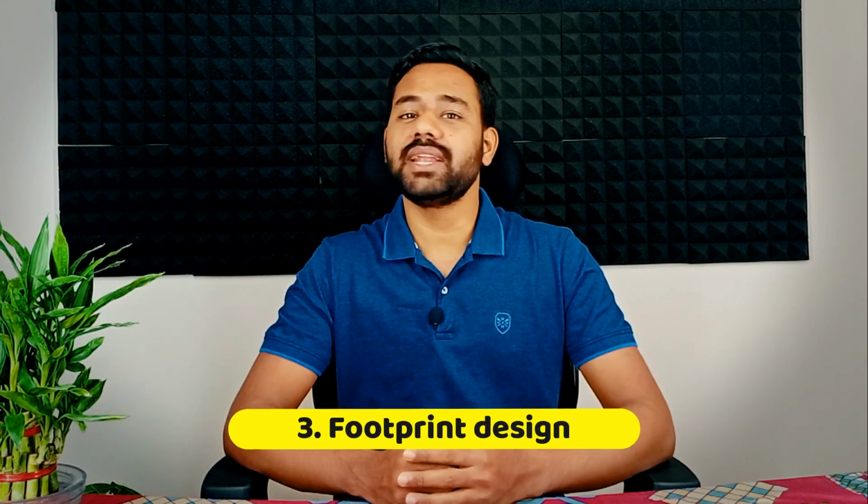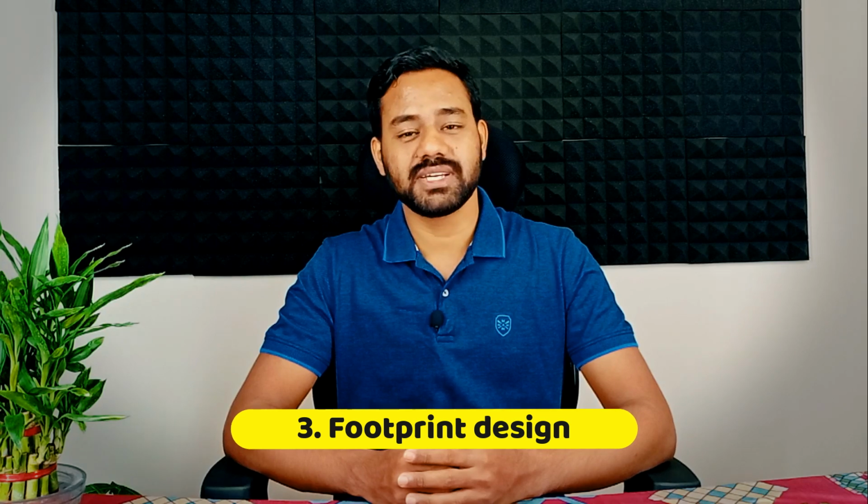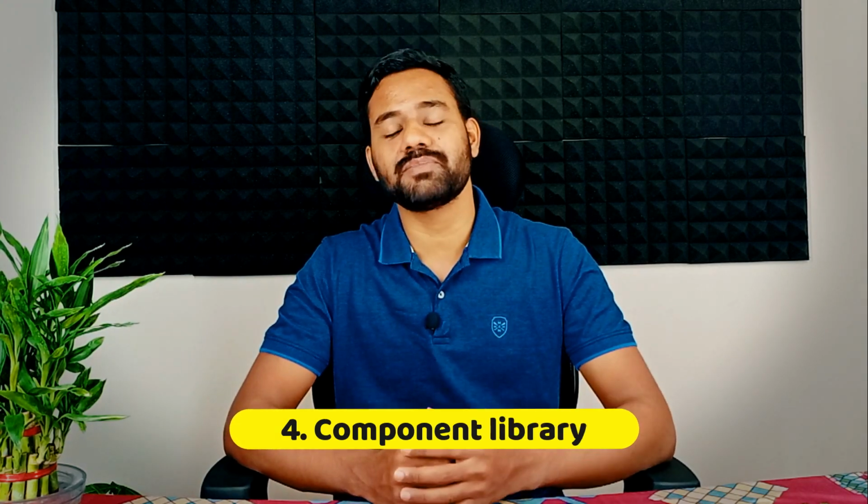Third step is creating a PCB footprint using the EasyEDA tool, in which we are going to refer to the datasheet for mechanical information as well as dimensions, and again we are going to follow the Cartesian geometry and create an SMD version of the Atmega328P footprint. Last but not the least, fourth step is to combine the PCB footprint and a schematic symbol to create a component library in EasyEDA. So let's get started.